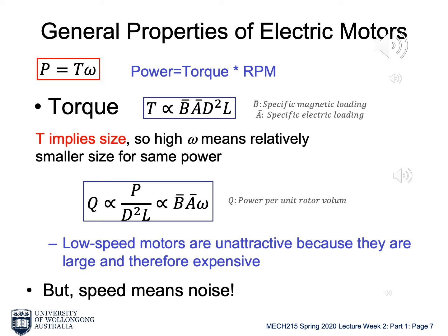And this leads to why in all these mechanical systems, we have a gearbox after the motor for a certain application. Because the combination of a high-speed motor and a gearbox for reduced speed is going to be smaller and more economical than designing a motor with very slow speed and using the motor by itself. Economically, that's much more beneficial. That's why we design a motor and then the gearbox.